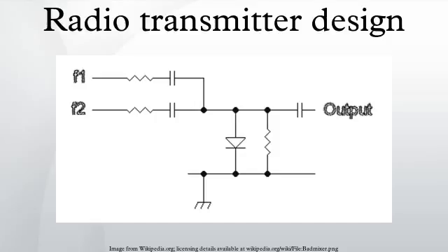The harmonic output of a transmitter is best checked using an RF spectrum analyzer or by tuning a receiver to the various harmonics. If a harmonic falls on a frequency being used by another communications service, then this spurious emission can prevent an important signal from being received. Sometimes additional filtering is used to protect a sensitive range of frequencies, for example, frequencies used by aircraft or services involved with protection of life and property. Even if a harmonic is within the legally allowed limits, the harmonic should be further reduced.